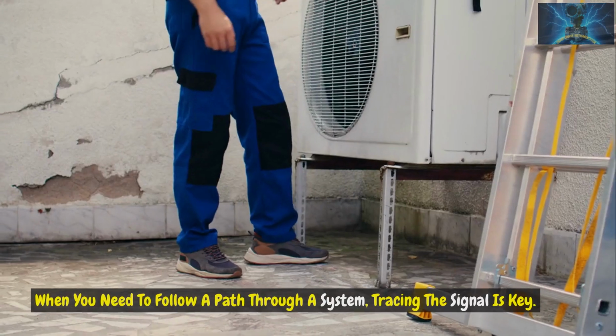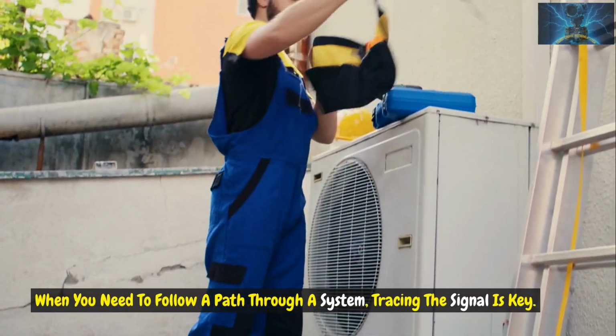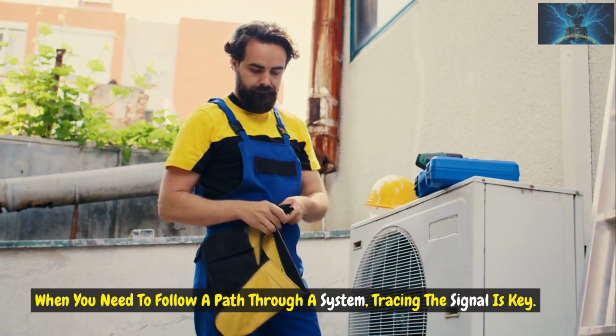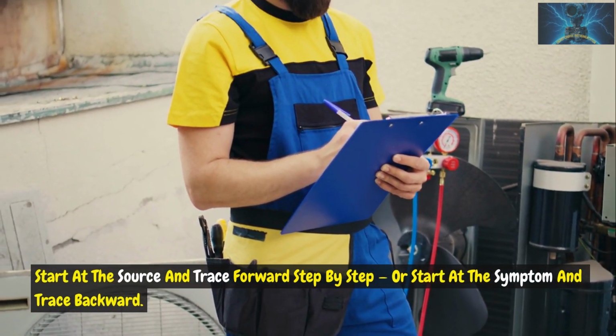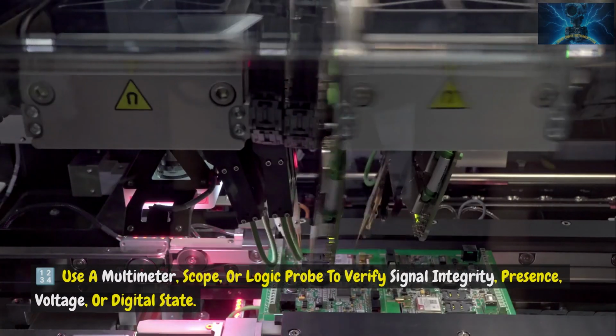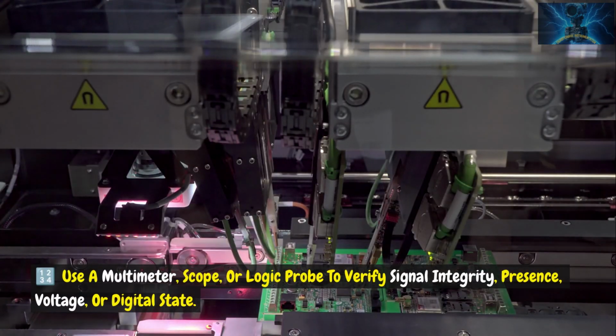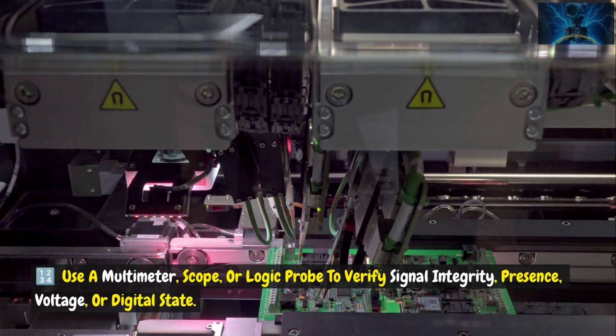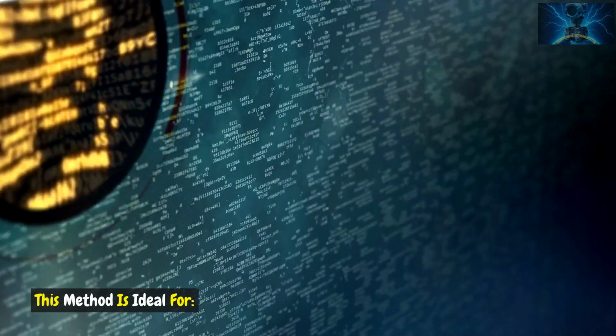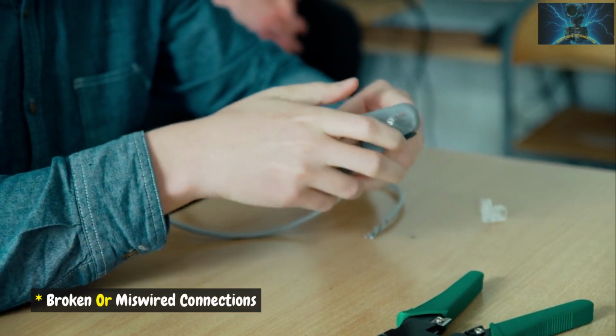Signal trace. When you need to follow a path through a system, tracing the signal is key. Start at the source and trace forward step by step, or start at the symptom and trace backward. Use a multimeter, scope, or logic probe to verify signal integrity, presence, voltage, or digital state. This method is ideal for broken or miswired connections, terminal block errors, and open loops in analog or digital systems.